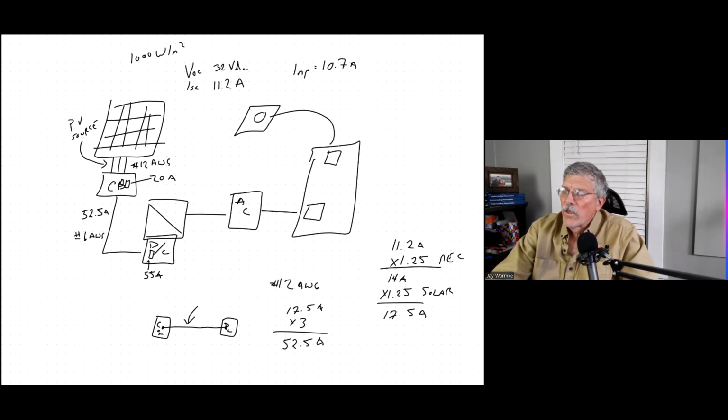So we wouldn't want to use a 30 amp box. So we'd probably use the 60 amp. And if it's already connected to the inverter, it's going to be sized based on the capacity of the inverter. So that's just the metal itself within the box. How much amperage can it handle before it melts or it does something bad? So in this case, I've got a 60 amp box, a 55 amp fuse being fed by number 6 gauge wire. Okay, so I've sized the wire there.